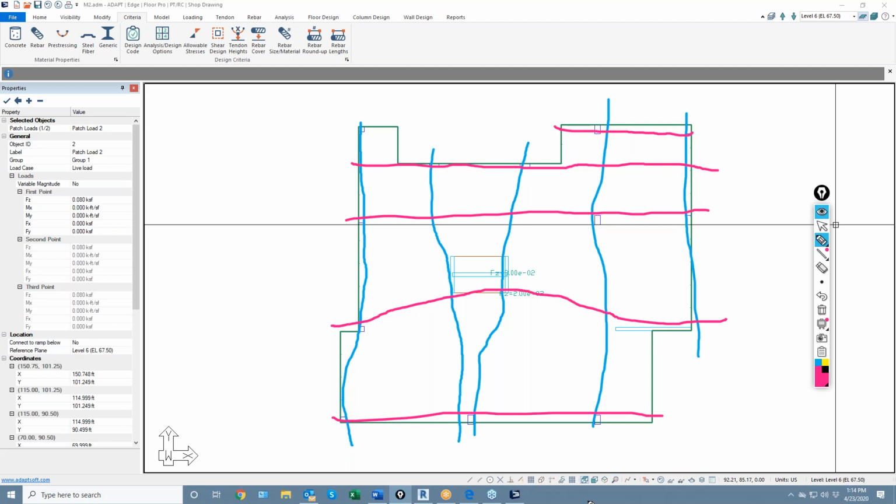For this slab, I'm actually going to represent all of my distributed cables as 4-foot groups of cables every 4 feet. So if I have a 4-foot section here, this is 48 inches, and I say I want to target at least 125 PSI pre-compression for this unit section, by calculation we need 1.7-some cables per 48 inches.